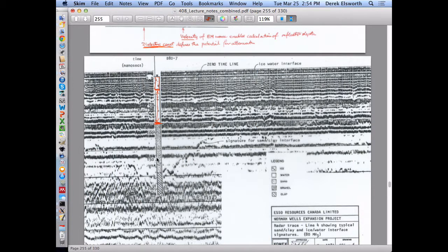So this is water, and then beneath the water there's sand, and beneath the sand there's clay. And so you have that from your borehole. In this particular case, these were drilled with a diamond drill core barrel, and the sand was not sampled. It just came up disturbed, but the clay was hard enough that it could actually be drilled into, and plugs of it were retrieved. So now that you have this borehole, you absolutely know what is physically here.